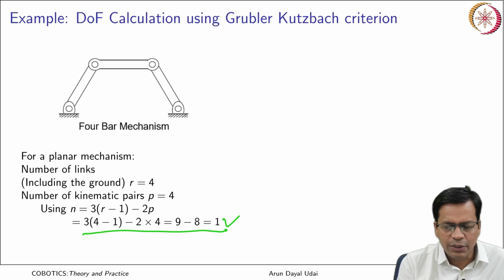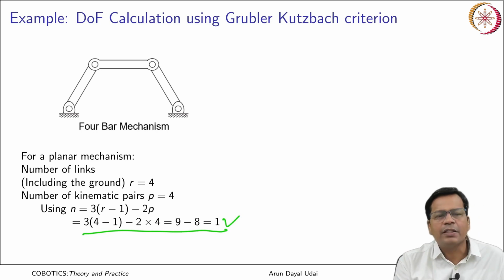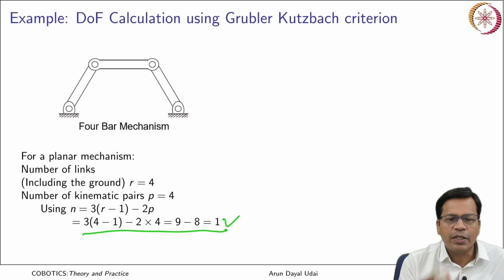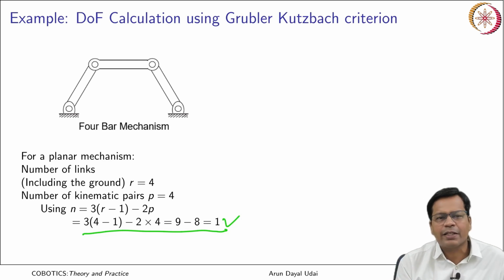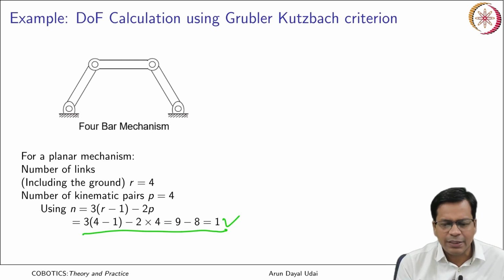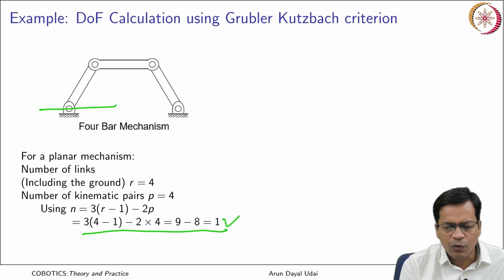So, over here you see, can you apply the degree of freedom definition here? The number of independent constraints needed to fully define the system, or the number of independent constraints that I can put so as to fully constrain this system. So, let us just weld one of the joints. If I weld this one, I have put a constraint here.